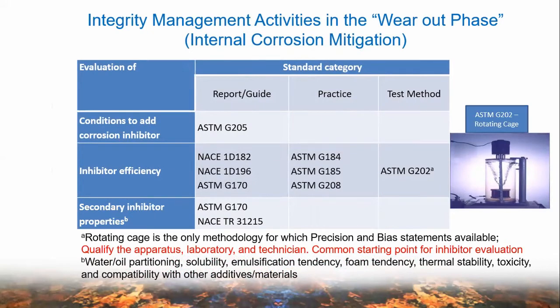If the models and experience indicate a higher corrosion rate, then you need to implement mitigation strategies. Strategies to mitigate internal corrosion include use of cleaning pigs, addition of corrosion inhibitors, and application of internal coatings, and among them, application of corrosion inhibitors is predominant.